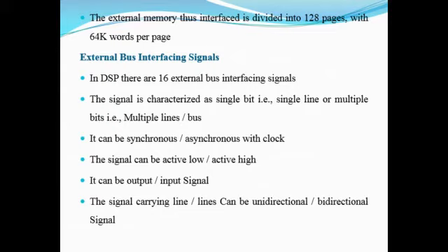So these signals which are generated can be characterized as a single bit or single line, or multiple lines or multiple bits, also referred to as a bus. And it can be synchronous or asynchronous with the clock. And the signal can be active high or active low.